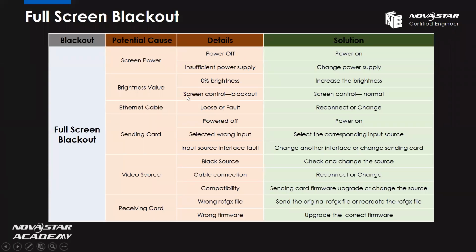Also in the LED software, in the screen control interface, we need to check if the setting is blackout. If it is, we need to change the setting to normal. For the Ethernet cable, sometimes if it is loose or if there is something wrong, we need to reconnect or change another Ethernet cable.